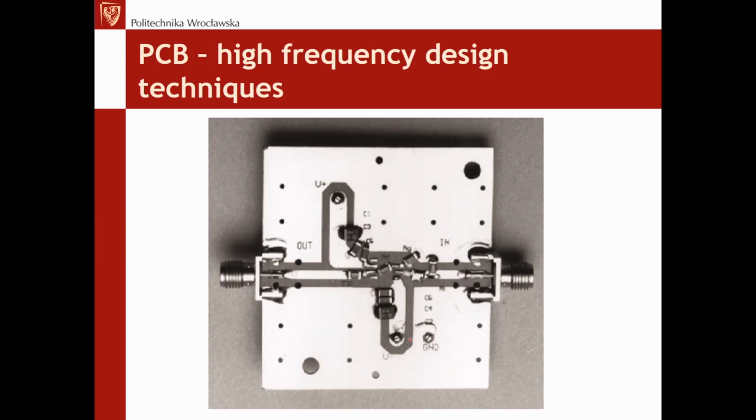Here we have an example of a very simple high frequency board with plenty of ground plane. This is the ground plane, no vias on the path. Take a look, no vias here, just a plane. So connectors, input output, and some tracks with controlled impedance,